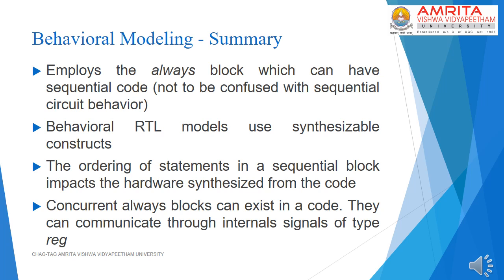Now to sum up, the always block provides the framework for behavioral modeling of digital systems. The behavior of a digital subsystem can be modeled using sequential statements. Here the term sequential refers to the sequential execution of statements inside the always block, and it is not to be confused with sequential circuit behavior.